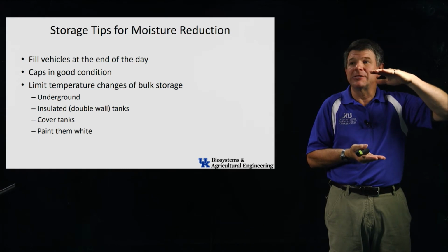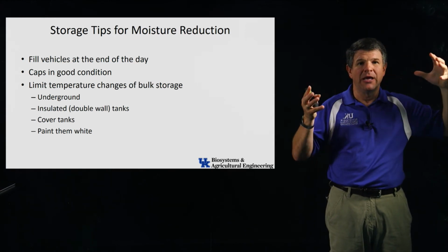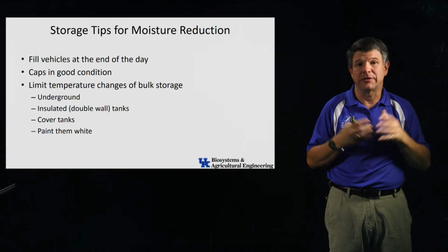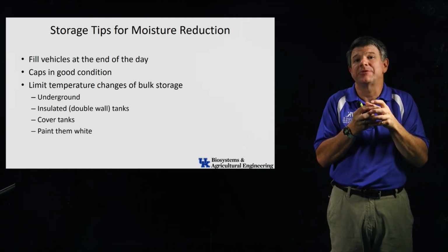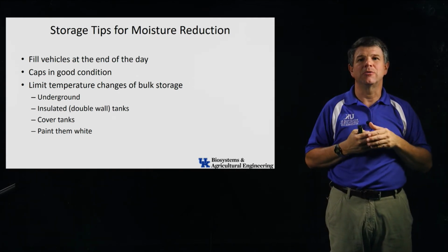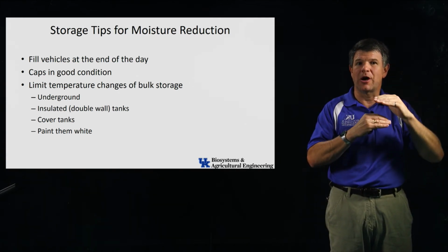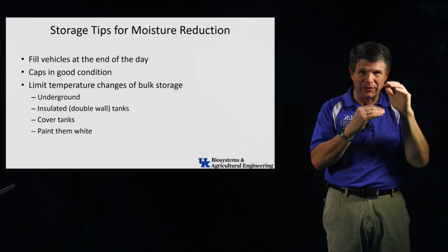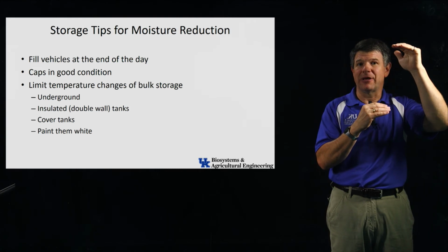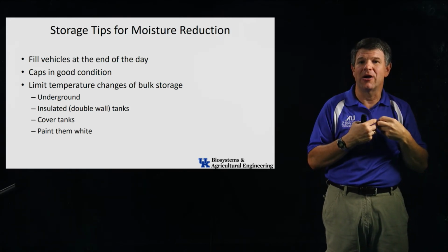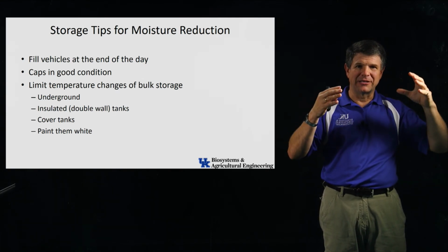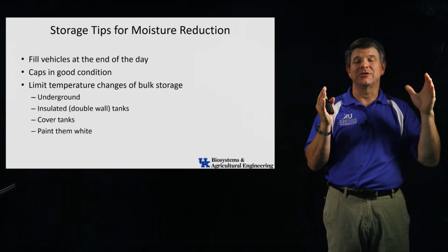If I've got a lot of headspace above the fuel in the tank, as that air cools off, it's going to shrink. And since we have vents in the tank so that the tank doesn't collapse, it's actually going to pull in ambient air. What happens when it pulls in cool ambient air? When that air cools off, if the dew point temperature is relatively high, the relative humidity will be pretty high on that fuel. So we're pulling a lot of air into that tank, and as that tank cools off, we're going to get condensation on the inside of the tank.